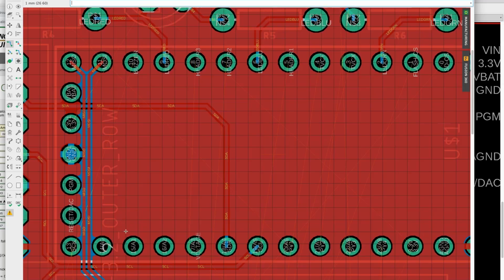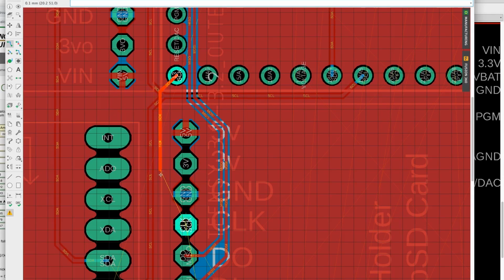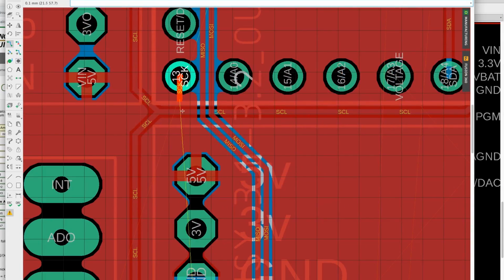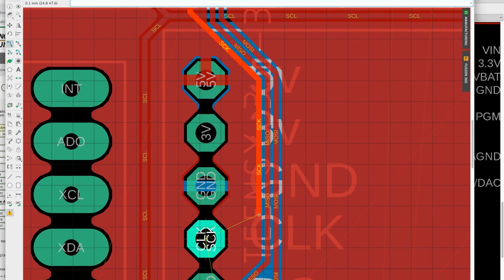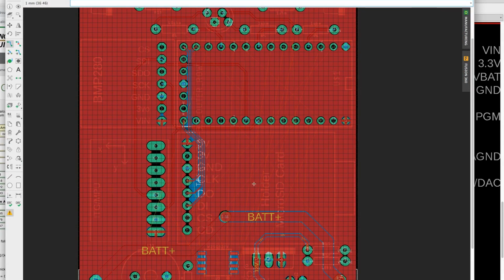And we have one more, which is, where is it here? It should be the SCK line. Oh my gosh, where is it? There it is, 13, SCK. So we'll take this signal right here. I'll click that, and then I'll route it down to, oh, SCK is right here. Actually, what we can do is click the SCK line and just send it right along with the MISO and MOSI lines. We'll route that down to the CLK or SCK line. We'll hit rat's nest, and now we have SPI connection to the SD card.